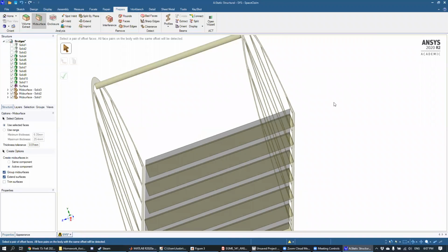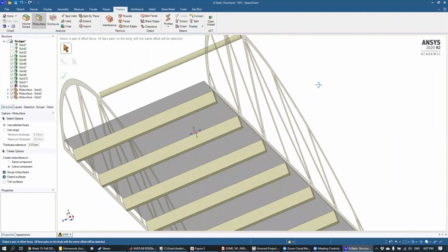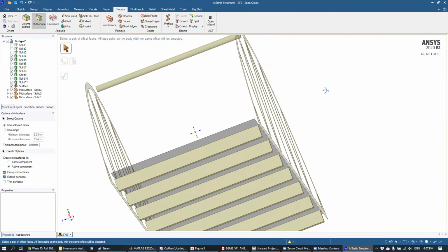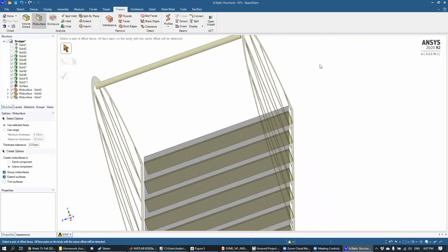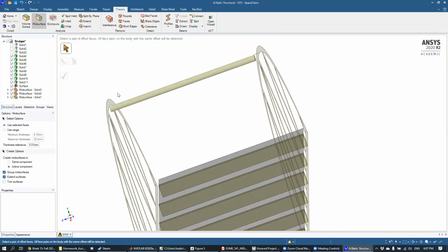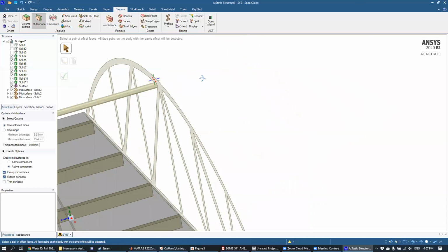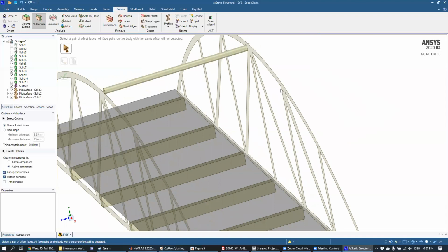And so now let's go over beams. You can see here we have a lot of geometries that would work well for beams. In this case, we have actual literal beams, so we have structural elements here. But anytime you have a part of your geometry which has one length that's much longer than any other dimension, like here, where this is much longer than it is wide or tall, those types of geometries are great for beams.